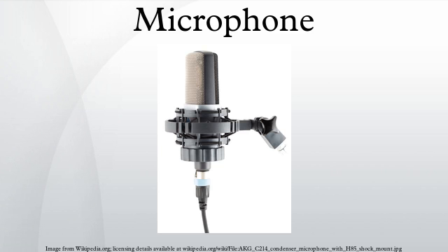The Baudet microphone, which used relatively large carbon balls, was similar to the granule carbon button microphones. Unlike other microphone types, the carbon microphone can also be used as a type of amplifier, using a small amount of sound energy to control a larger amount of electrical energy. Carbon microphones found use as early telephone repeaters, making long-distance phone calls possible in the era before vacuum tubes.